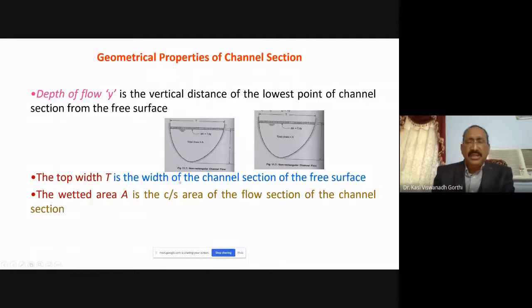This top width is the width of the channel section at the free surface. For the section figure given here, an arbitrary shape, this is the free surface. So the width measured from this point to this point is called the top width T. Then the wetted area A is the cross-sectional area of the flow section of the channel.